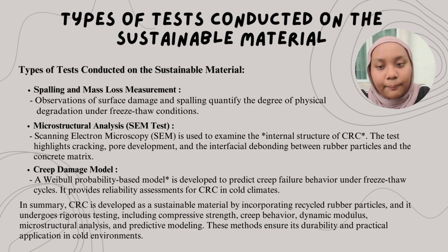Number 5. Microstructure analysis (SEM) test. Scanning electron microscopy (SEM) is used to examine the internal structure of CRC. The test highlights cracking, pore development, and the interfacial debonding between rubber particles and the concrete matrix.